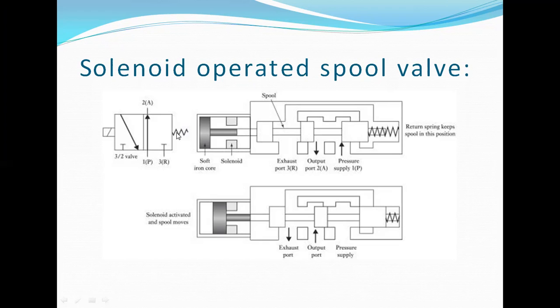Here, with the mechanical spring return, in the forward stroke when this valve needs to be operated, this solenoid will be energized, and at that particular time this force will be obtained. Simultaneously, tension will be created in the spring. When it retracts back, it releases the already existing stress or contracted force. And simultaneously, this second position will be continuously applied. The second position, in the sense, is the position with the connections of first port, second port, third port.